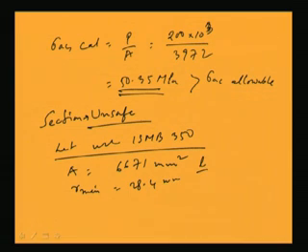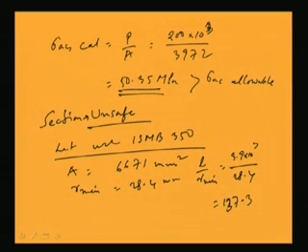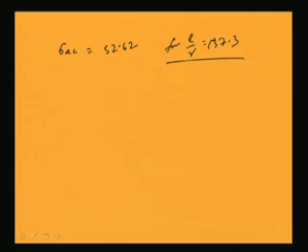So lambda, L by R minimum, will be 3.9 into 10 cube by 28.4. This will become 137.3. Now from table 5.1 I can find out sigma AC value. This will become 52.62 for L by R as 137.3, from the interpolation of the data given in table 5.1.